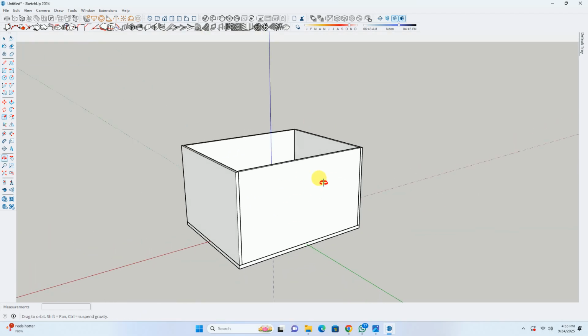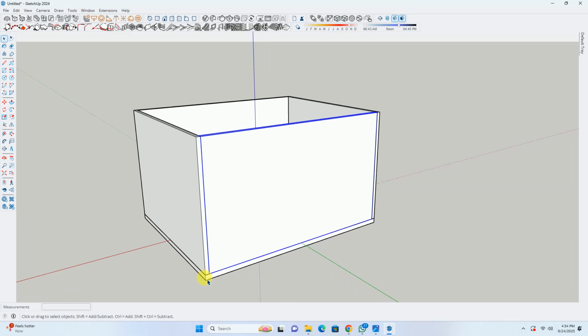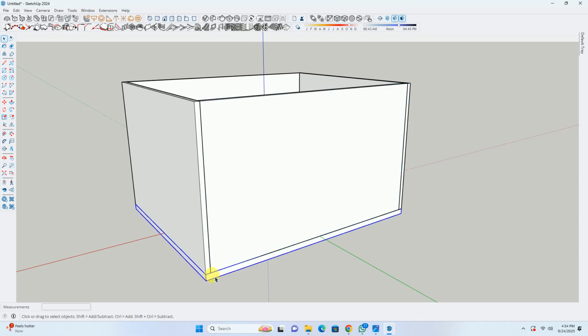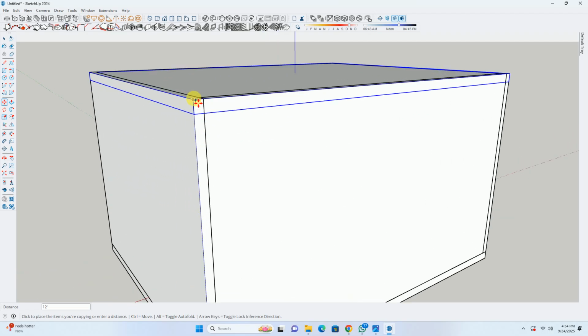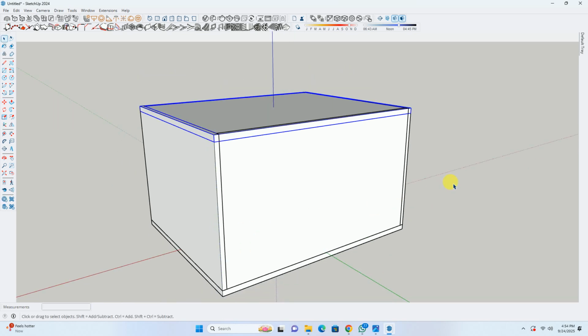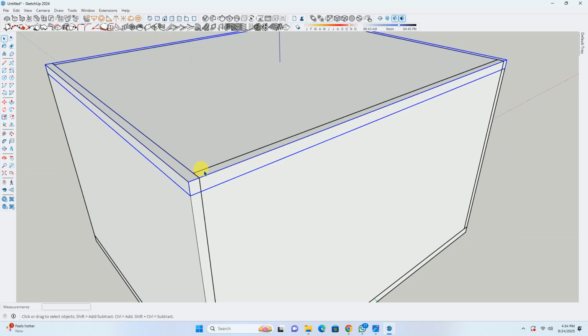Now, after creating this, we have to create a surface ceiling at the top. For that, I will copy the base slab. I'll move it, or I can apply the copy command. I'll apply copy from this particular top point, and I'll hit the control key so that I can get multiple elements. Now I'll specify the top point at this particular top. Now we can see this ceiling and wall are getting merged with one another.